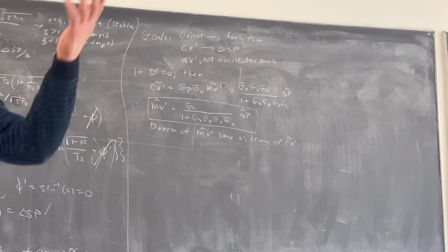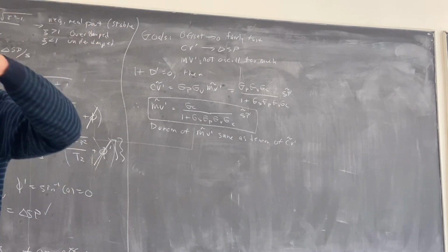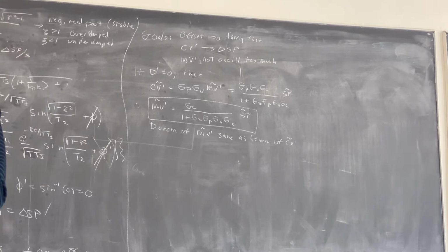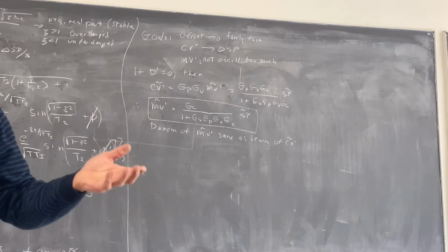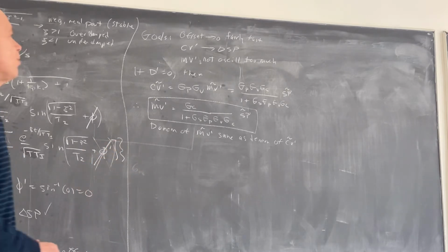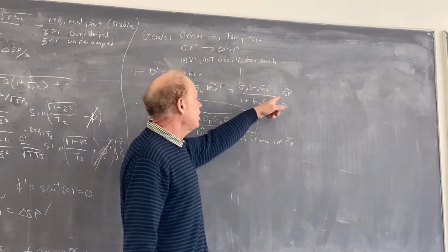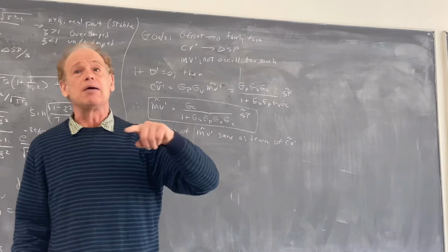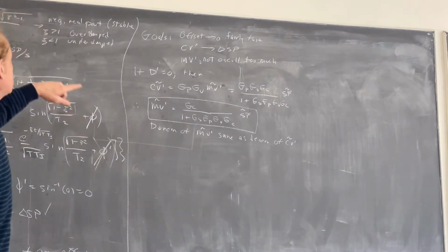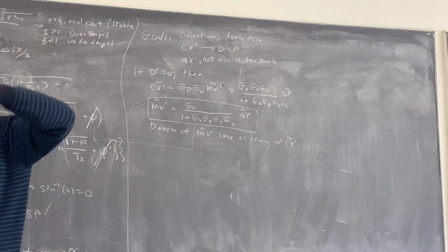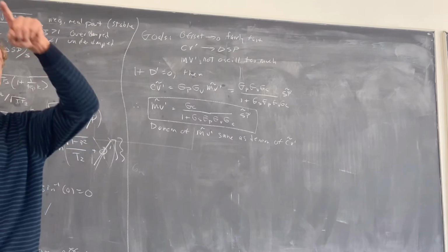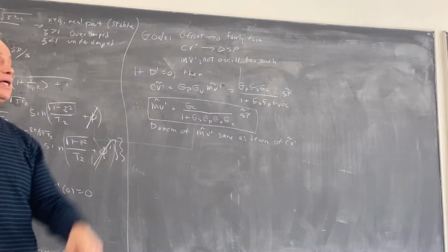That is, if CV starts going crazy, going off to infinity, then the valve is going to be either completely shut or completely open, and it's still not going to be enough. But it also tells me that if CV prime oscillates, so if it's underdamped, even if it's decaying, it oscillates quickly and decays.